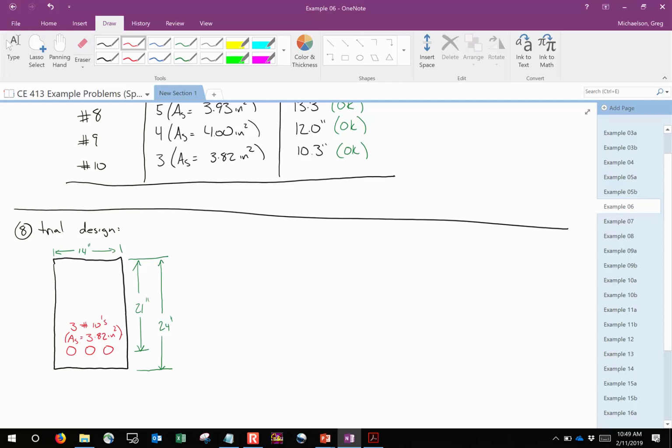Another thing we're going to have to do is straight analyze this beam: compute the capacity, compute the phi value, see if we meet the area of steel requirement, and then ultimately compute an efficiency. We're going to do that next time. Because that isn't going to take too long, we're also going to extend this design process a little further and ask, what if we already knew the cross-section of the beam? What if we were using something like a precast beam or ready-made formwork where we already knew what the beam looked like, and the only thing we needed to determine was the area of steel? We're going to use the same design aid, but the process is going to be a lot simpler.